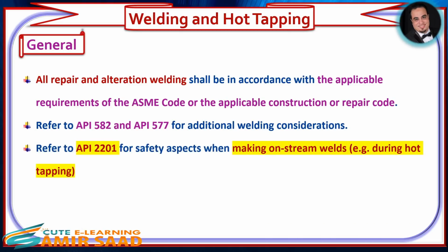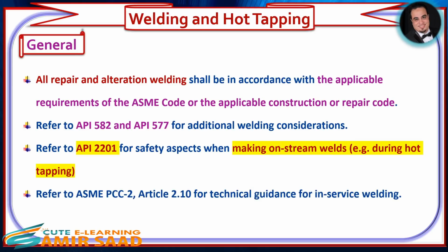Refer to API 2201 for safety aspects when making on-stream welds, for example during hot tapping. Refer to ASME PCC-2, Article 2.10 for technical guidance for in-service welding.